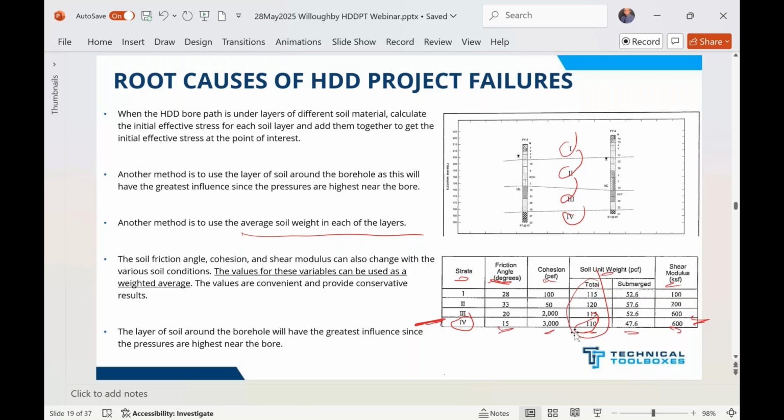No, there are no calculations that check for delamination. Now, if you're pulling in your high density polyethylene plastic pipe, again, you typically don't have a coating on that. And that does calculate the pull loads on the pipe and the stress, but it doesn't calculate any type of coating stress for steel or plastic or anything else.